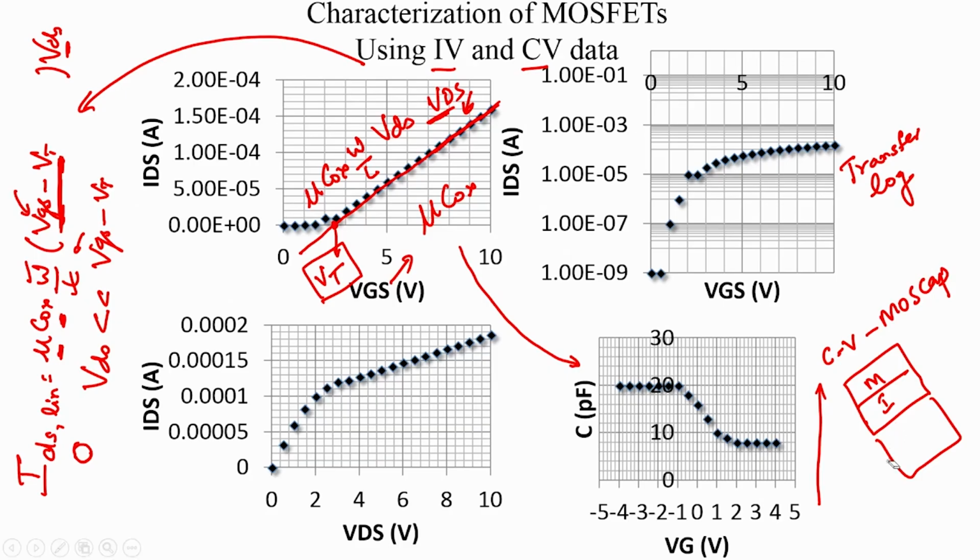But on the other hand, in the case of a MOSFET, the source can also inject electrons. So, you have the source and drain. It is also possible for electrons from the source to enter the channel, and therefore, it is likely that these electrons will appear at the interface on time, and that these electrons can respond to the applied AC signal. And therefore, it is possible that you still see a low frequency measurement in a MOSFET at the same frequency corresponding to a high frequency curve of a MOS capacitor. Okay.